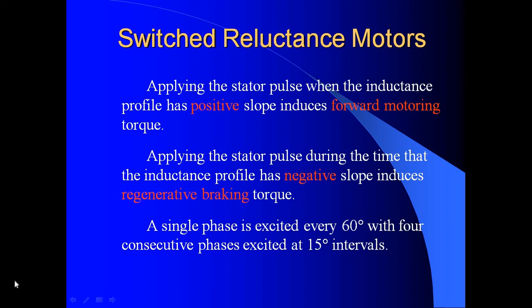Very good morning. Today we are discussing the switched reluctance motor. Applying the stator pulse when the inductance profile has a positive slope induces forward motoring torque. Applying the stator pulse during the time that the inductance profile has a negative slope induces regenerative braking torque.